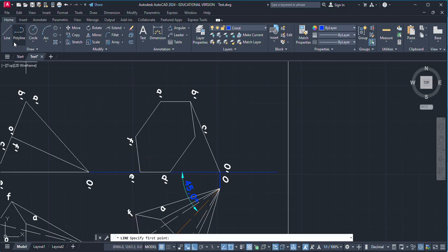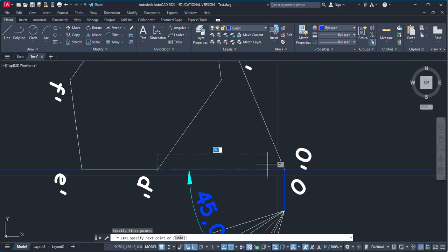Now connect all the edges, slant edges, this one here. Now we need to draw this here because this E dash O dash slant edge is actually behind the body, so it will not be visible. It is not going to be visible, so no need to connect these two lines. We have already created this D dash O dash.